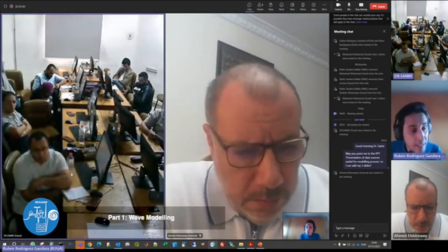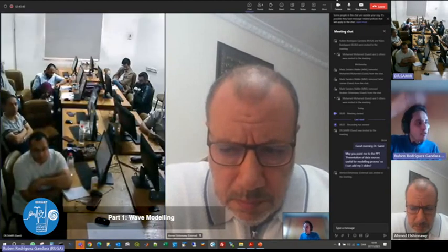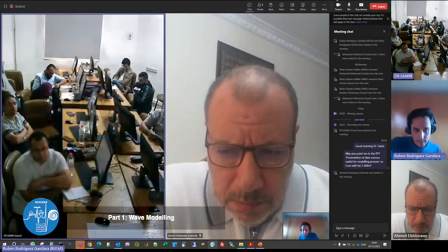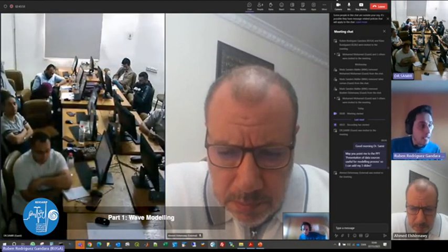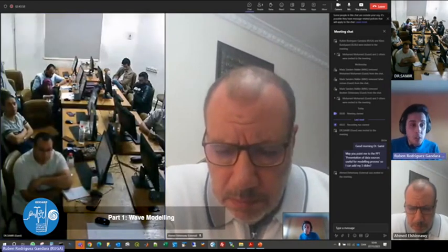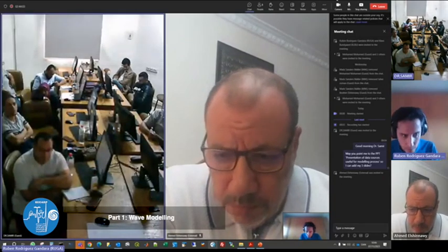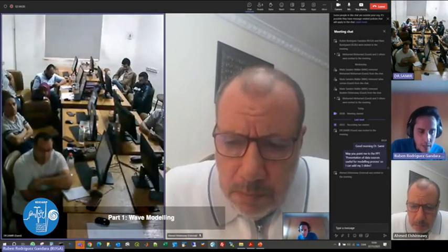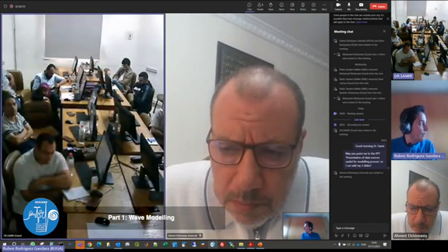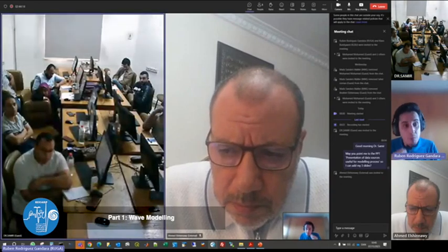While with Mike 21 Spectral Wave, where you don't have to resolve the phase, you can run, let's say, 40 years of hourly sea states as forcing at your boundary in, let's say, 5 days or 1 week, if you have enough computational power. That's something that you cannot do with a phase resolving model like Boussinesq or mild slope, because it takes way more time.